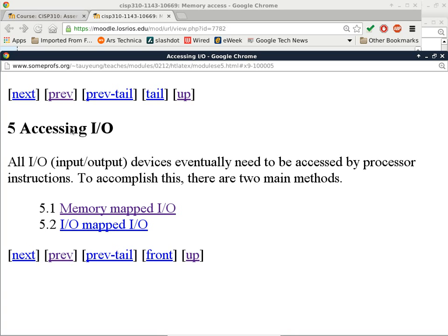Some locations are also special. When you write to those locations, you will actually be generating an output from a certain device. Like in the good old days of serial communication, there's a data register associated with a serial communication chip. When you write to that location, the circuitry will actually clock out the ones and zeros onto the serial bus, otherwise known as RS-232 communication. So that's how a program can talk to I/O devices.